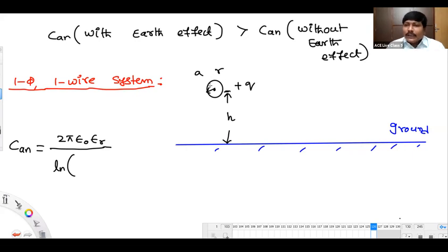Already we have taken the forward conductor. Where will be the return conductor? So if you have only one conductor like this in capacitance calculation, definitely we should take the image conductor, and then only we should consider the capacitance calculations. So I'm showing that image charge below the ground. It is A dash, and it's minus Q. And again, this is also at a depth of h.